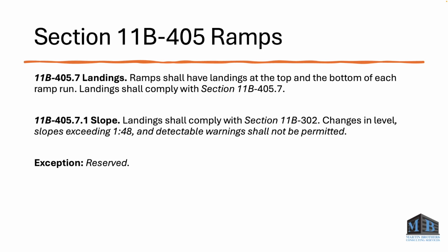They may be provided outside of the landing, but we really want to avoid the situation where a ramp dumps you out into the vehicular way where you would need those detectable warnings, because that's hazardous. Ideally, there would be some form of physical separation, either a wall, another bit of sidewalk, something in between the ramp landing, grandma coming down in her wheelchair, and the road. Yeah, so let's keep it going.